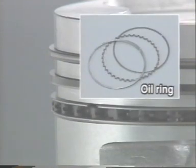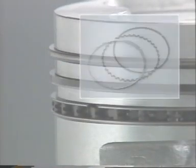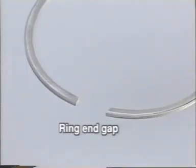The lowest ring, the oil ring, scrapes oil off the cylinder wall, leaving the minimum necessary oil film thickness on the wall to prevent excess oil from entering the combustion chamber. Every piston ring has a ring end gap to allow for ring expansion. The end gap is 0.2 to 0.5 millimeters at ordinary temperatures.